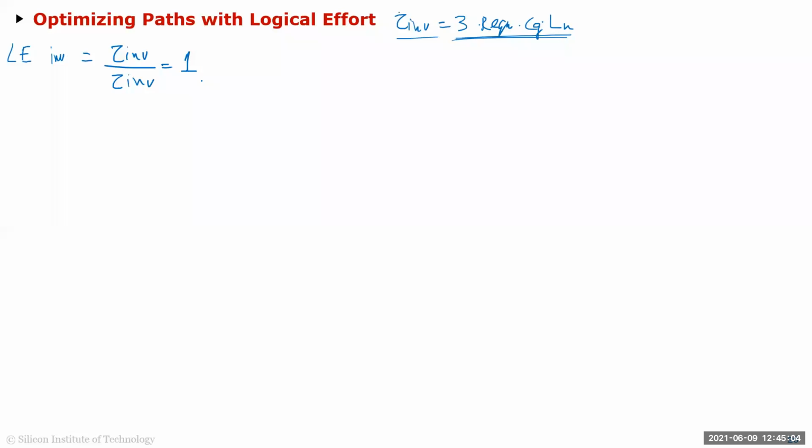So the logical effort, we are going to define this logical effort as the inherent delay of a certain gate divided by the inherent delay of the fastest inverter, basically. So for the inverter itself, it is 1, like you said. And for the NOR gate, LE of NOR would be tau of NOR divided by tau of inverter, and then LE, the logical effort for NAND, would be equal to tau of NAND over tau of inverter, right?